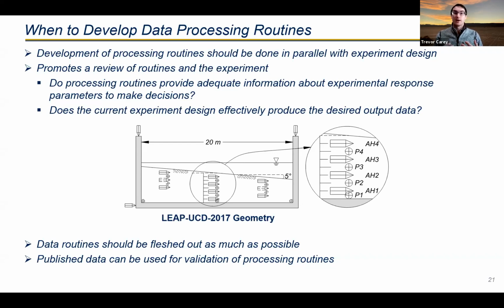One of the important parameters from these experiments was stress strain data. And stress strain data in centrifuge experiments typically comes from an inverse analysis procedure using accelerometers, which are shown here with these pins. By walking through the process to do inverse analysis for stress strain data, you'll start to see that if I have my sensors placed too far apart, I may not get the resolution of data that I need.